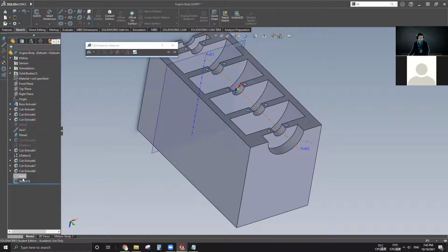But in this case, the axis is referencing this feature, and this feature is all the way right here. So if we try to move this axis all the way above, you see the little enter sign became an invalid sign. So this is how far this axis can go. It cannot go above. All right, this is kind of important, so I hope you guys stay awake and can memorize this.